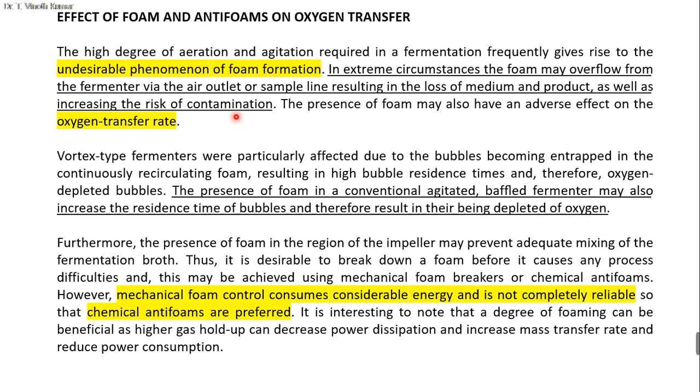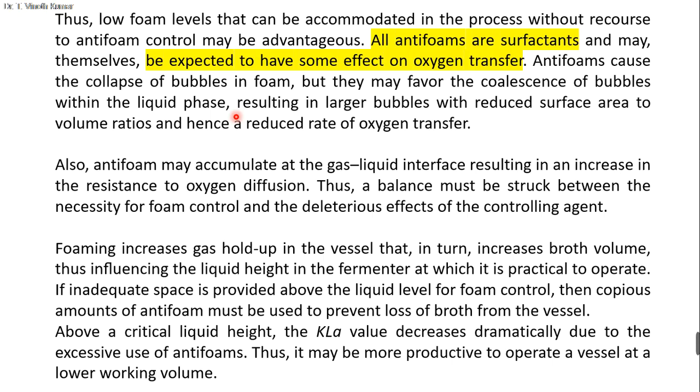Chemical antifoams may be better when compared to mechanical foam control, because mechanical foam control is time consuming and may create a lot of complications related to contamination. The chemical antifoams are surfactants. Surfactant means it will reduce the surface tension and be expected to have some effect on oxygen transfer.